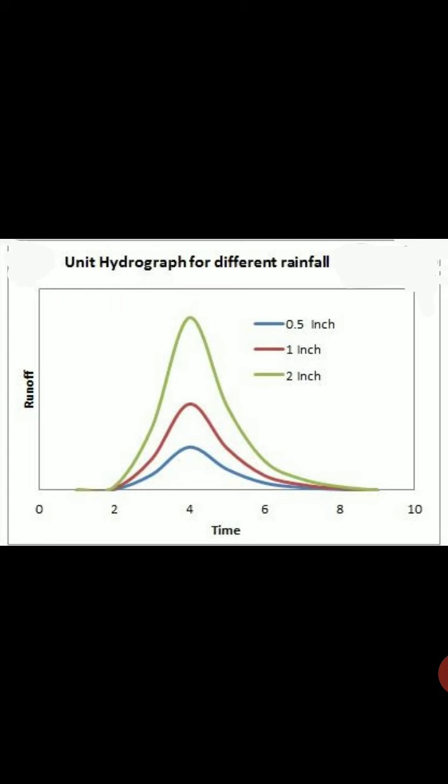So what are the uses of unit hydrograph? Uses of unit hydrograph are in many hydrological problems, such as in the development of flood hydrograph corresponding to design storms which are required for the design of hydraulic structures.